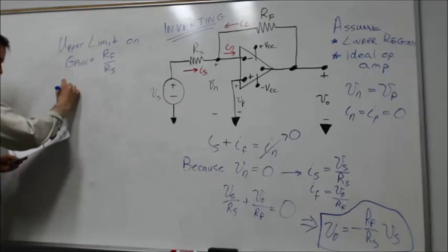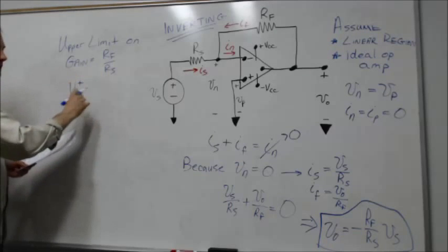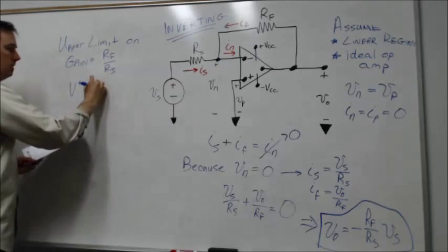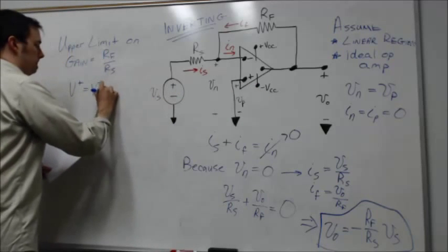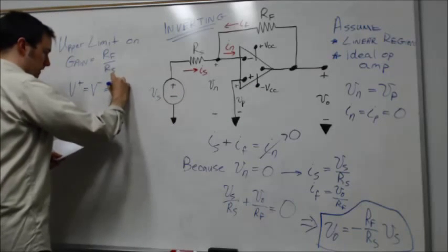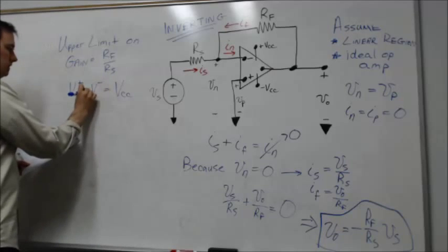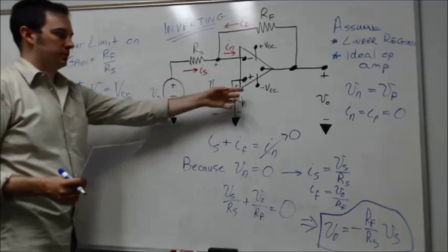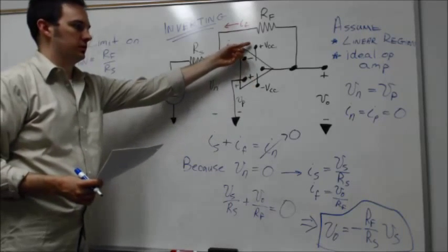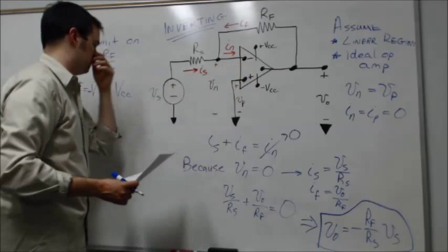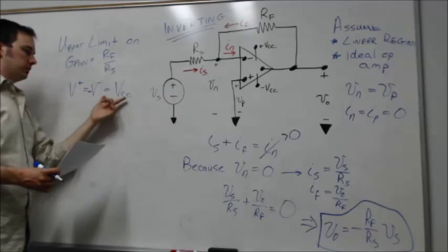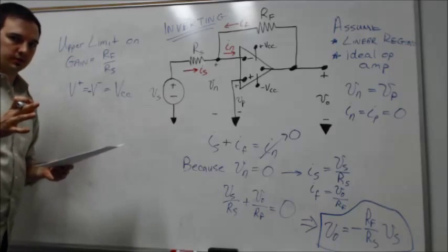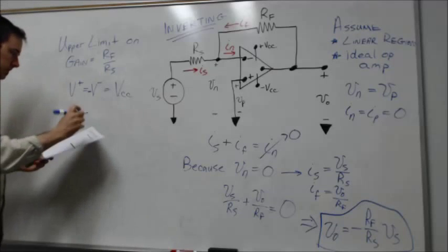And so we start out by making the assumption that V plus here, which is basically the positive VCC, is equal in magnitude to V minus, the minus VCC, some quantity VCC. So the magnitudes of the voltages are the same but they're opposite polarities. We're going to work under that condition, which, as I said last time, is not necessarily always the case, but typically makes things a little bit easier.